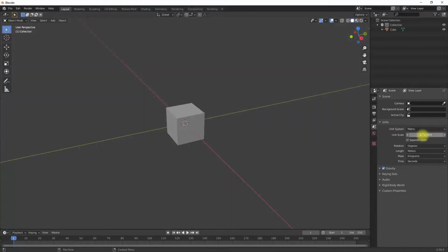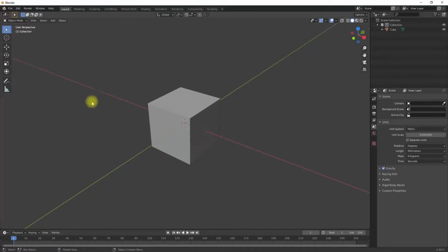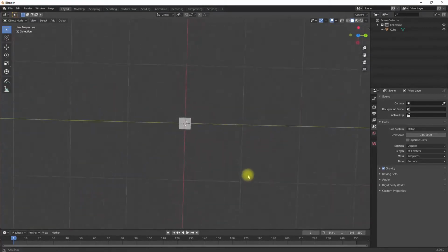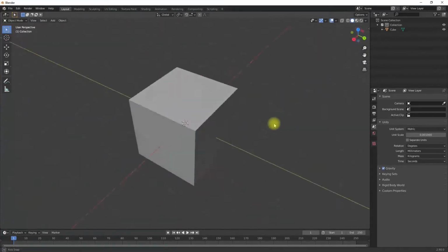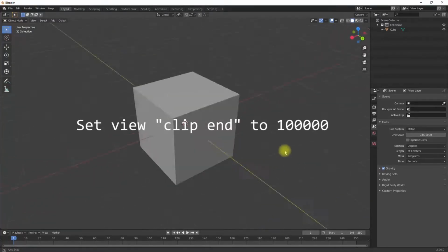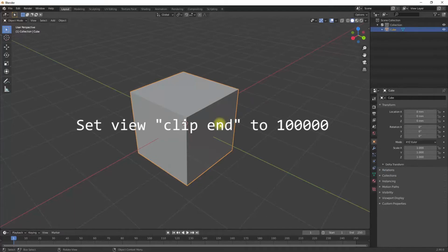Then I adjust the measuring system in the scene settings. In my case, metric with millimeter as a unit. This also includes that the size of the viewport grid should be set to the same scale, so you can use the grid snapping to model exactly, using the orthogonal perspective and absolute grid snapping.